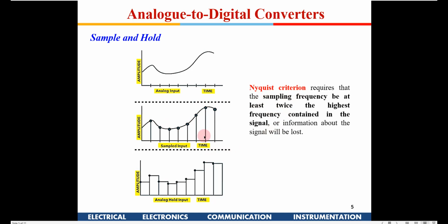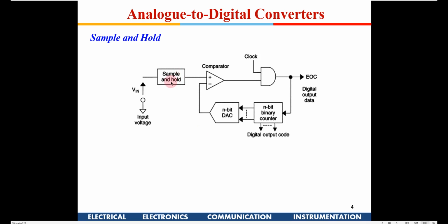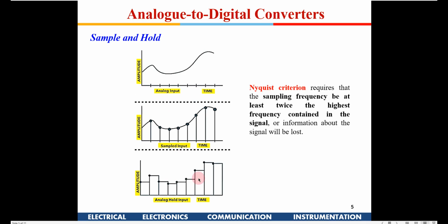So that is not an issue. The only thing we need to be careful about is that when we are sampling signals, we sample at a frequency at least twice that of the input signal. You don't have to continuously transmit the entire signal. So this sample and hold thing will work fine. Okay, so that is what this says.